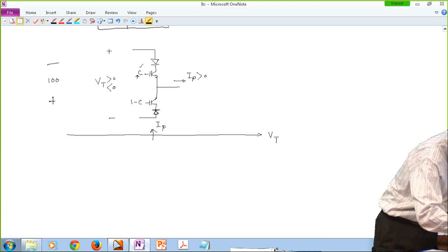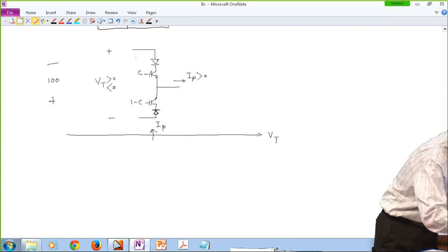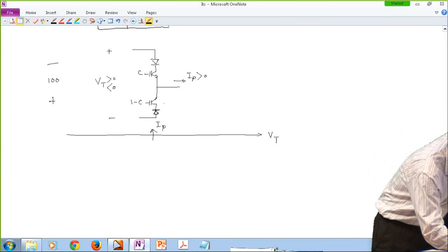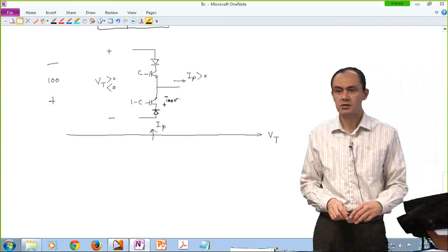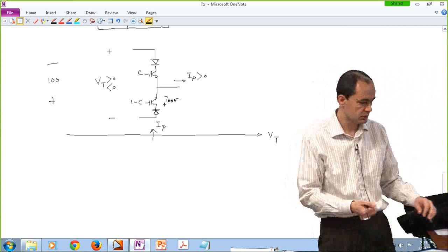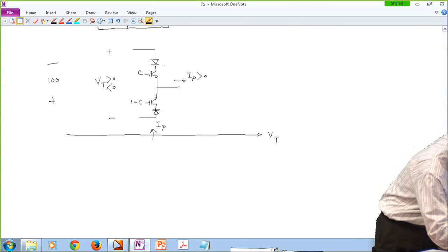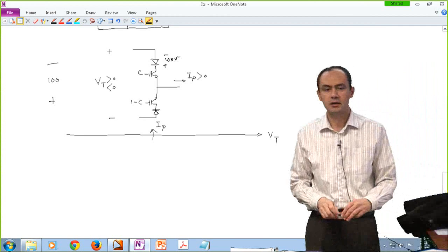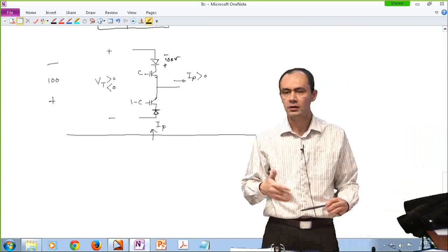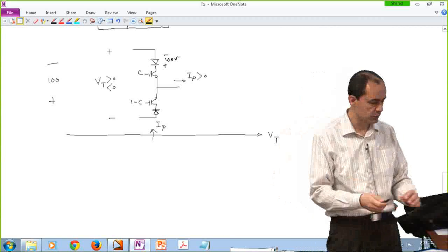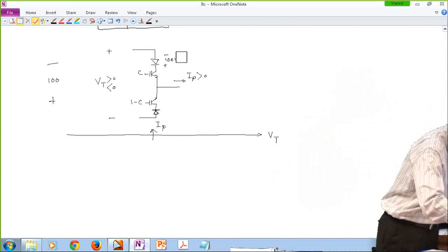If the voltage is negative in this polarity, let's say the top throw is engaged, and in that case, we have 100 volts appearing here. So the bottom transistor is blocking the voltage. If the bottom throw is engaged, then we have this diode reverse biased, so it's blocking that negative voltage. So no matter where we are, there is at least one component that is blocking the negative or positive voltage, so we don't have to worry about things getting out of hand.